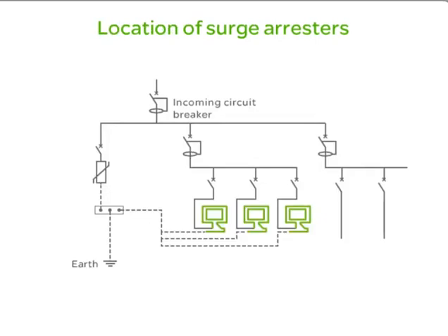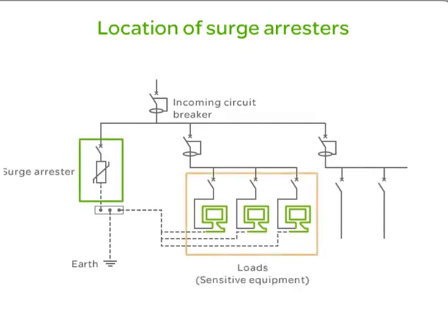For protection against transient overvoltage, a surge arrestor must be installed as far upstream as possible from the low-voltage electrical installation. This is in order to divert overcurrent to the earth and thereby prevent it from spreading downstream of the installation.